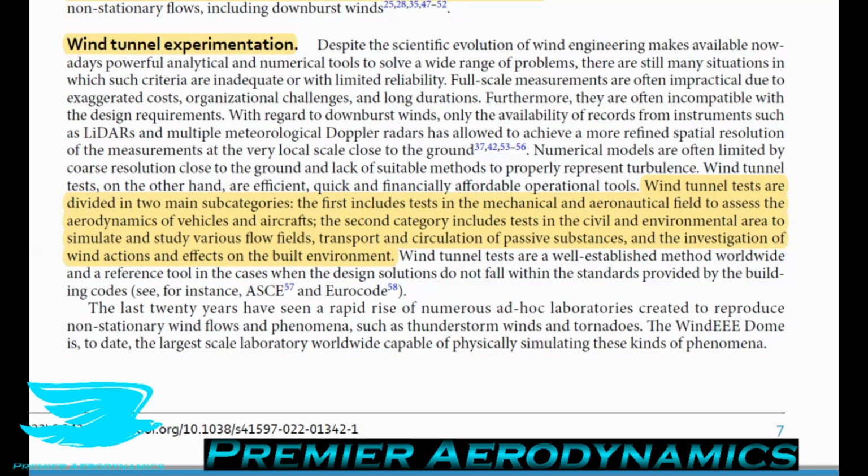Another major difference is the boundary layer. Again, if we think about what's happening on Earth, on the surface, we actually have a boundary layer forming. So when you walk around outside, you're in a boundary layer. The reason is that wind comes along, going across the ground, and a boundary layer forms. It's very big. Typically, the boundary layer over the surface of the Earth is on the order of 100 meters tall. Even more, if you think about where the free stream velocity is, that's actually kilometers above the surface, and you can argue that the boundary layer is greater than that. But even still, the boundary layers are massive on the surface of the ground. So we want this same kind of thing happening in our environmental wind tunnels.